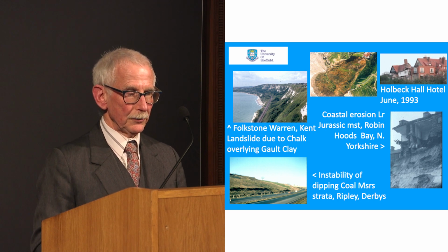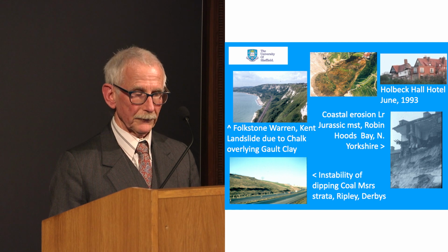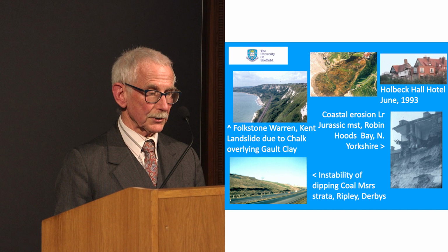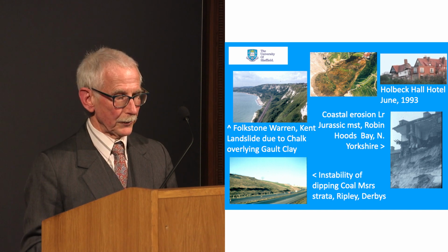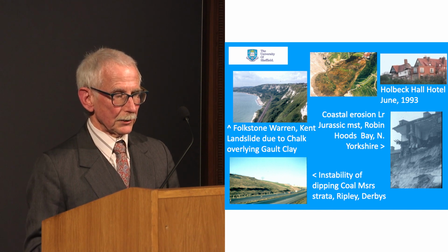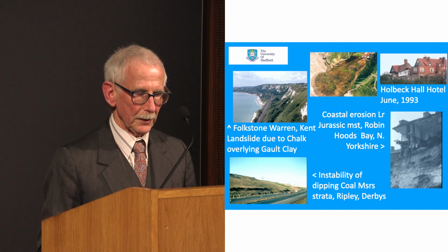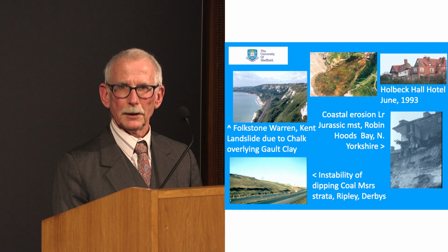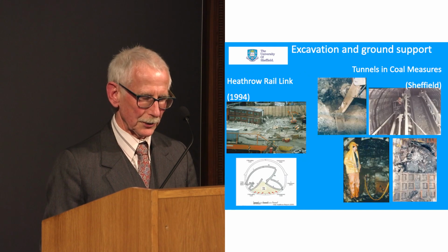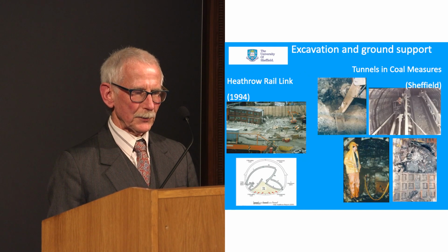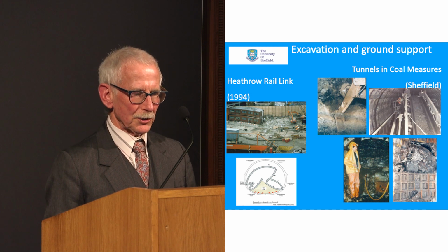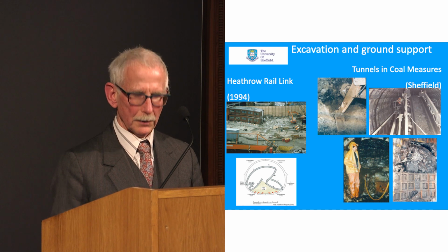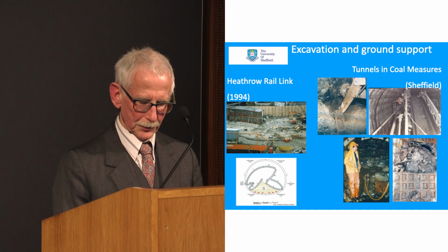In other cases, the excavated material can degrade rapidly during the excavation process to a slurry, which is then difficult to remove from the excavation, slowing down the tunnelling operations. In this case, slurry had to be taken out of the excavation using handwork with skips, which greatly delayed tunnelling operations.